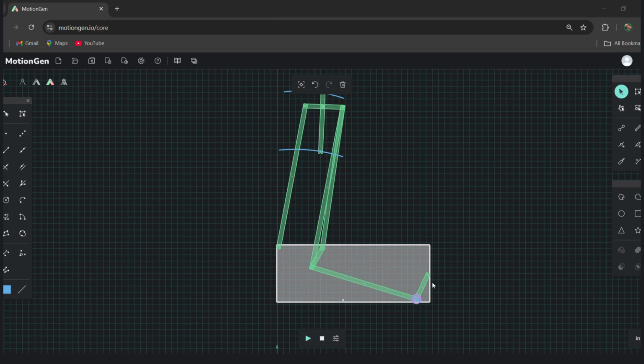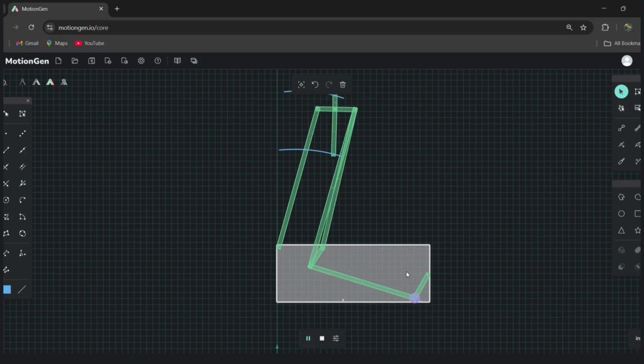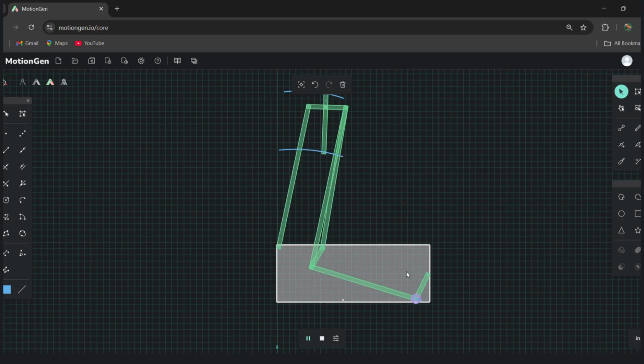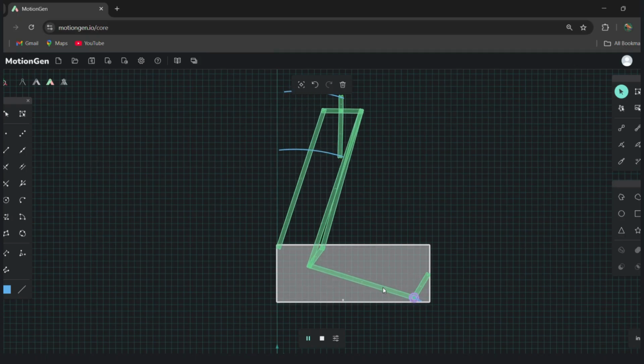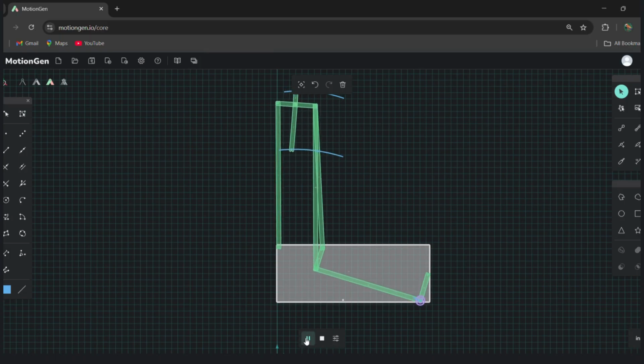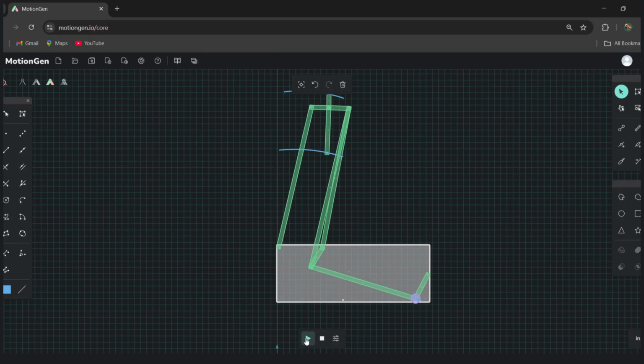However, when we violated the Grashof condition, that is when the crank was no longer the shortest link, the mechanism stopped working properly. The crank could no longer complete its revolution and the system locked. This demonstrated the practical importance of Grashof's law in real mechanism design.